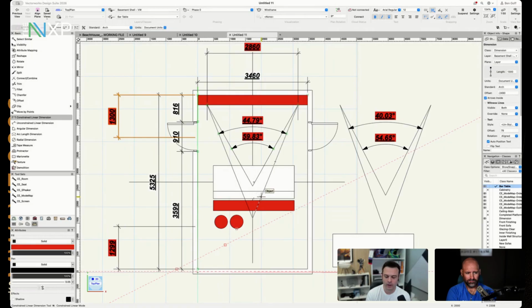The door should never ever, like, if you're not sealing it, any isolation you've done is null and void because all the air is just going out there. Yeah. So even a lightweight door, seals are $20. It's no money at all to put a rubber door seal around that door jamb. I'd still use a solid core door at the very least. Oh, sure, but irrelevant of what the door is, it should never rattle. Ideally. Yeah. Never. I'm not even going to say ideally. It should never rattle. If it rattles, go and do it again. It just shouldn't ever rattle. It's $20 to fix it, right? Just fix it.